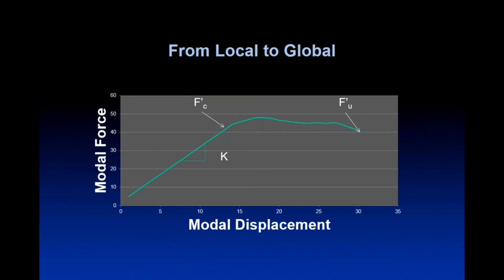I'd like just to show you this transfer from the small to the large. We're familiar with stress-strain curves, and the rate of rise here is the E value of the material that we're looking at. We've got the yield stress, which occurs at some place, and the ultimate stress at another place. That curve takes us from the linear elastic range into the plastic range. Now, what we're saying is, let's limit ourselves to this area here, just below the beginning of the plastic zone.